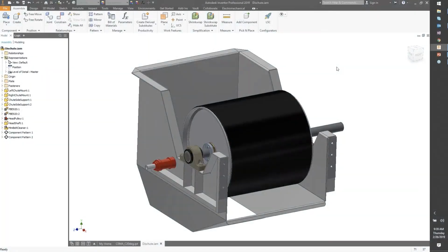Going back to performance, there are instances where companies think iParts and iAssemblies are the answer to their prayers in terms of simple automation, being able to quickly go to a table and change to a different iteration. And if you have multiple levels within your architecture of iAssembly, subassembly, subassembly, iPart, once again, that can impact performance.